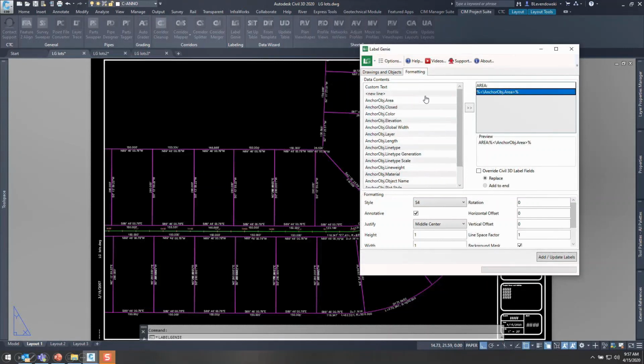So here I can spell out a custom field to be inserted into the M-text entity. I can put in custom text and then actually pull the field. This is an AutoCAD field that's going to automatically insert into every M-text object and read the polyline it gets inserted into. I mean, this is not rocket science, right? This is M-text on polylines, yet this is a huge pain in the butt in the software, right? So we're going to automate it here.